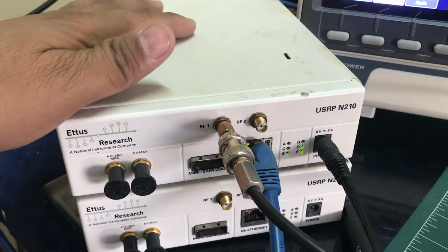I think 2 videos ago I made a video on how I can use USRP as a signal generator. There's a code available in UHD which is known as UHD signal generator. Based on that you can generate frequencies out from your USRP, and then you can connect an antenna or you can power up your circuit. So you can use your USRP as a signal generator.